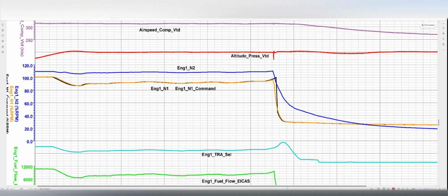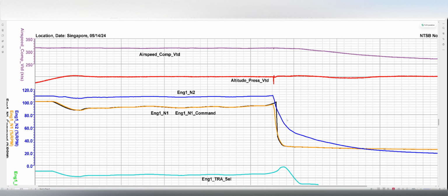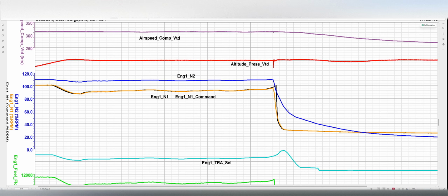Engine failure is detected when the aircraft's engines go below minimum idle. Here. This point. Flight idle would take less time because we're talking about 80%. So it took the N2 approximately, I'm going to call that 4.5 seconds from there to there, plus another 6 seconds to get from there to there. So to me, it looks about 10 seconds to get to 60%. 10 seconds it took the N2 to go from there to there.